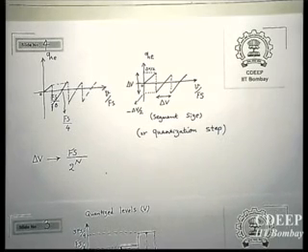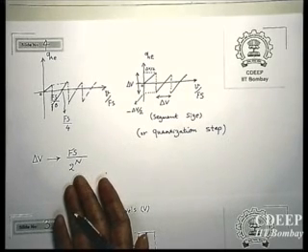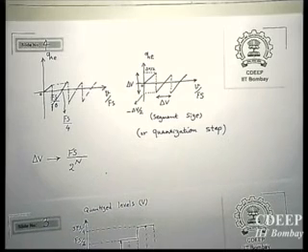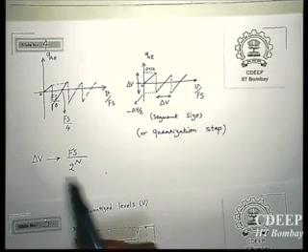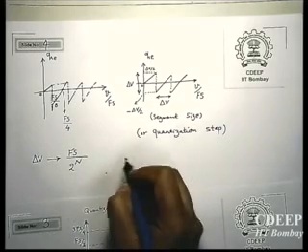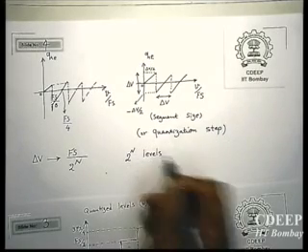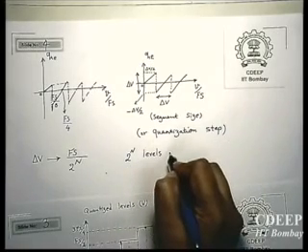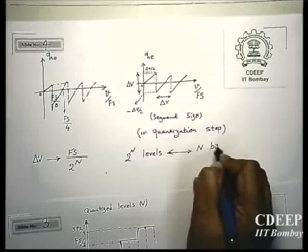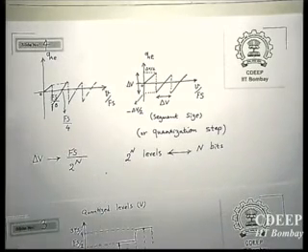So in other words, if I use n number of bits, I will be able to cover 2 to the power n levels, right? So that is correct. So eventually, if you generate 2 to the power n quantization levels, then this means that you can cover it with n bits, because it's binary, power 2.